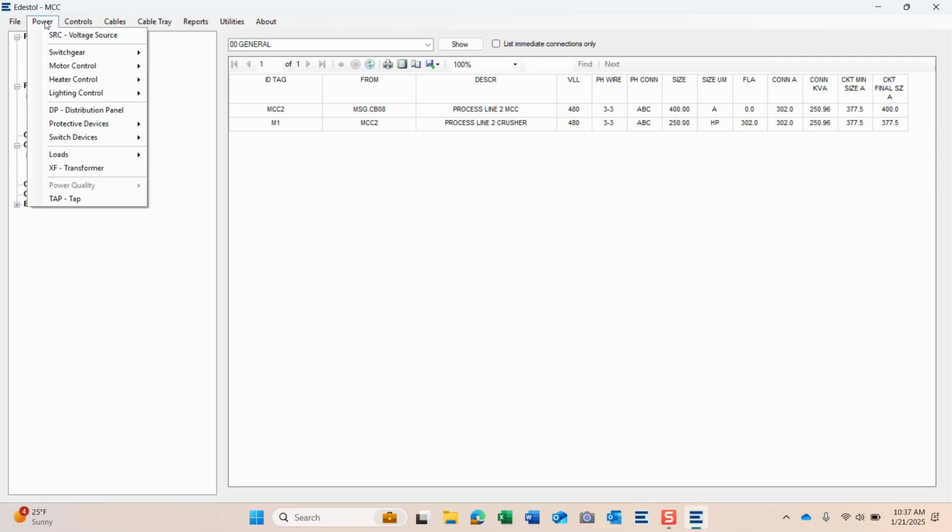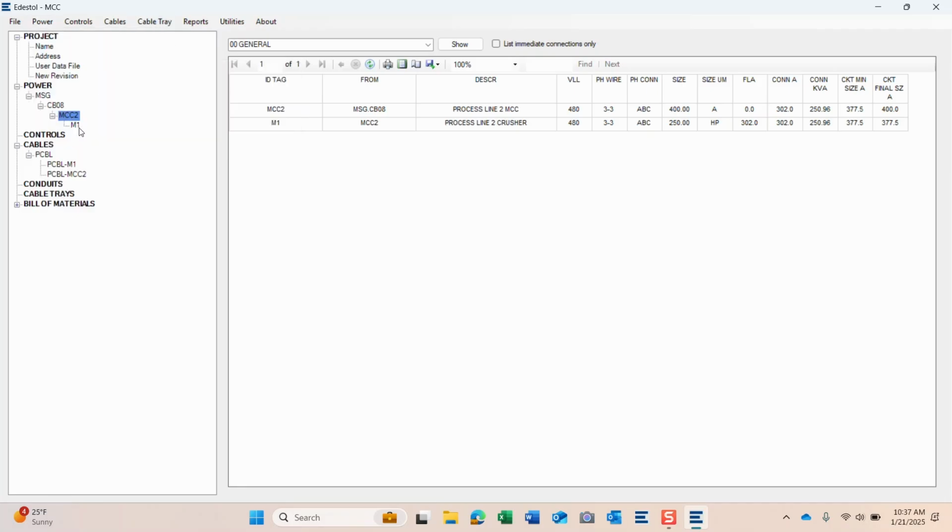You can also do a motor control panel. We'll get to that in another video, but you cannot just drop a motor on a motor control panel. You have to put in your power distribution blocks, your different protection devices, your starters, or your adjustable speed drives, whichever you need. So you can't do that, but with motor control centers, you can. The primary reason is that you'll have a list of motors but won't know the starters, so you can just drop your motors in and calculate your rough service size.